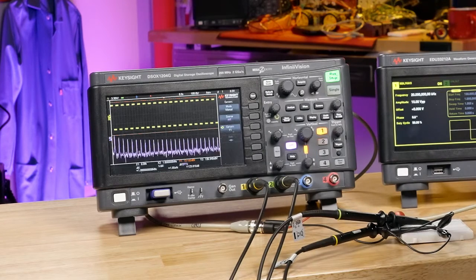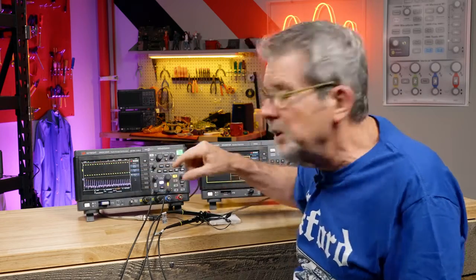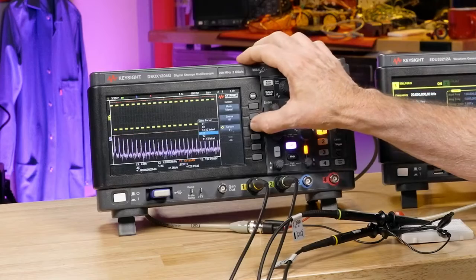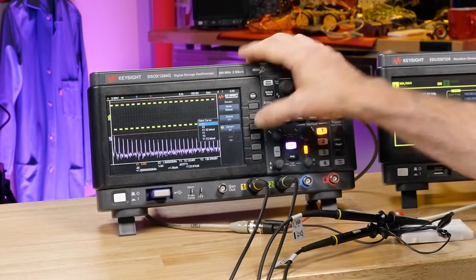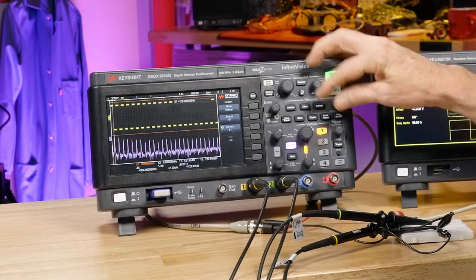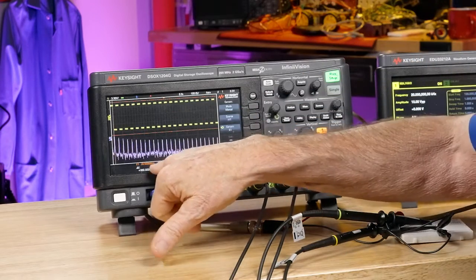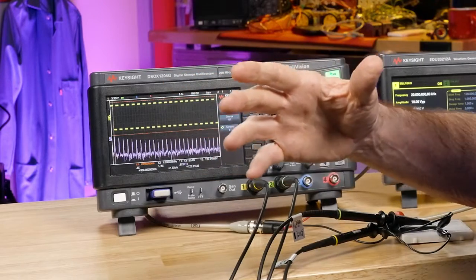13.13 dB volts. Now, you may not understand what dB volts is. I'll show you in a minute how we can change it to volts. And then let's measure the frequency of that one. Let's change it to X2 cursor and adjust that until it's right on top of the fundamental peak, and it measures 20 kilohertz, just what we expect.